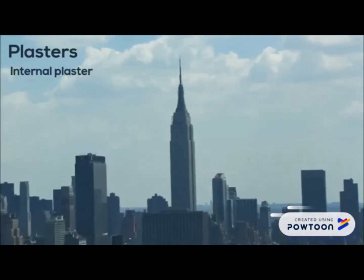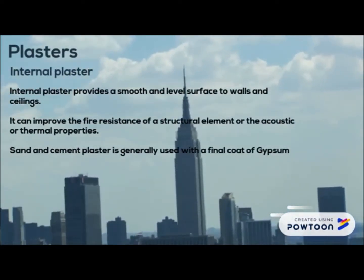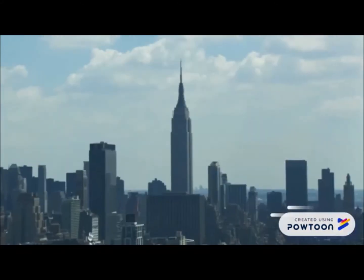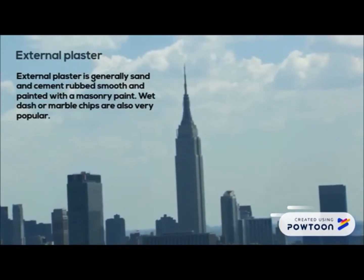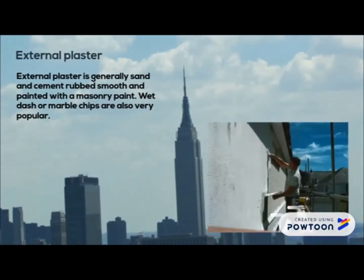Plaster. Internal plaster. Internal plaster provides a smooth and level surface to walls and ceilings. It can improve the fire resistance of a structural element or the acoustic or thermal properties. Sand and cement plaster is generally used with a final coat of gypsum. External plaster. External plaster is generally sand and cement, rubbed smooth and painted with a masonry paint, where dash and marble chips are also very popular.